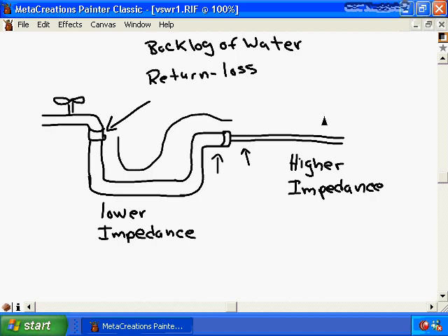Impedance is electrical resistance, and electrical resistance is measured in ohms. And you may have heard about ohms when you purchase speakers for your home audio system. So for example, if you're upgrading your home audio system to create a surround sound system, you want to check to ensure that all the speakers in your surround sound system have the same ohm level. And most speakers these days have a rating of 8 ohms, or have an impedance of 8 ohms. And the higher the number of ohms, the greater the resistance, and overall that will mean there will be less power that can be delivered by an amplifier.